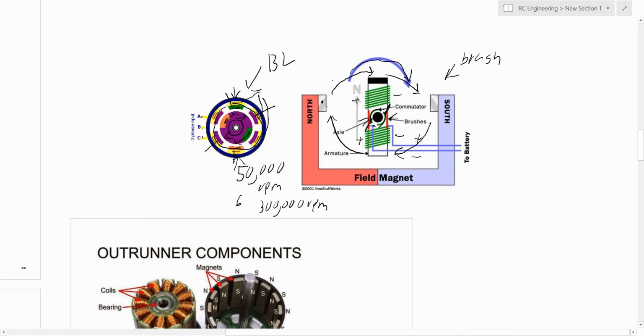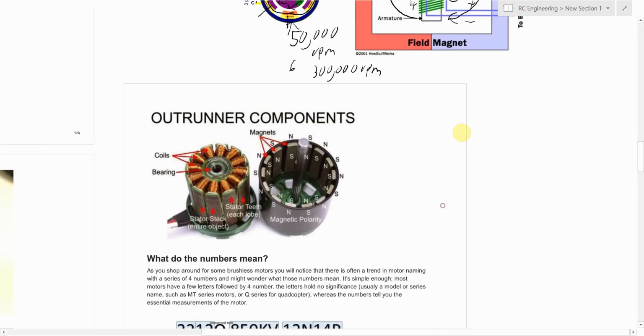And as you see, the timing is controlled physically on the brushed motor itself. So the only way the brush timing could be off is if it was designed incorrectly, so you don't have to worry about that. You just have to feed power to it and it will turn. Whether or not you want to control the speed, now that is a little bit more complex, but it's just a simple PWM through a transistor, compared to an ESC, where it needs to look at the back EMF on the motor to figure out where the stator is, or any sort of other complex timing.